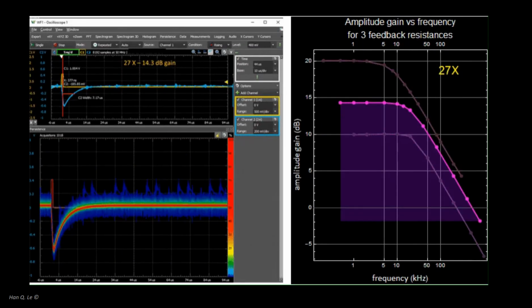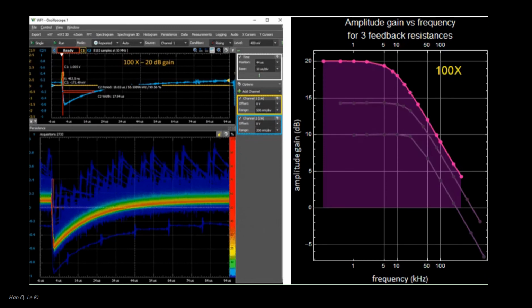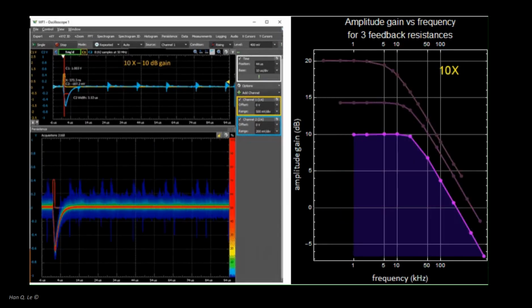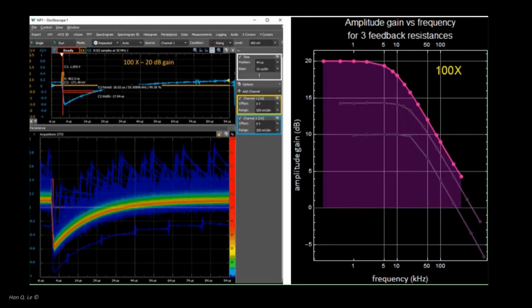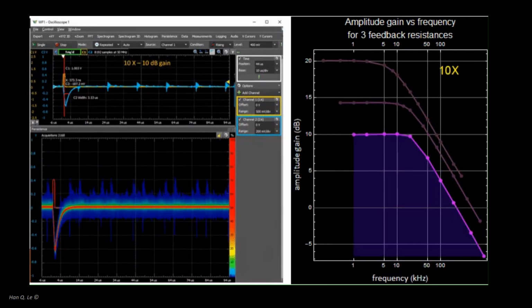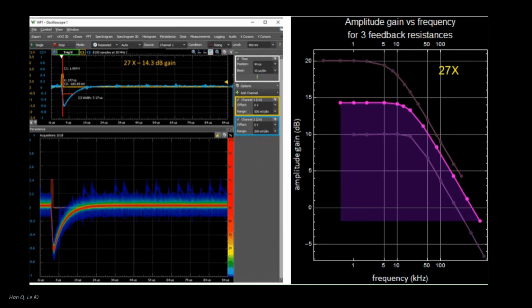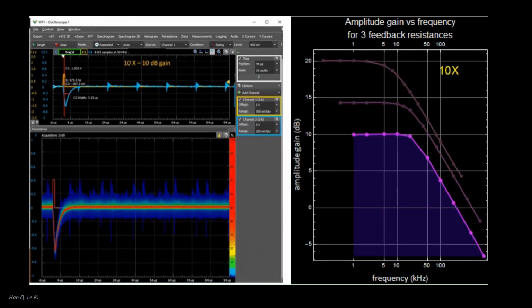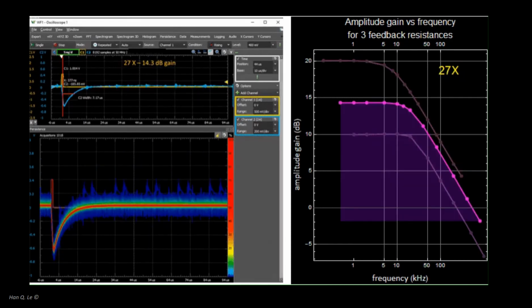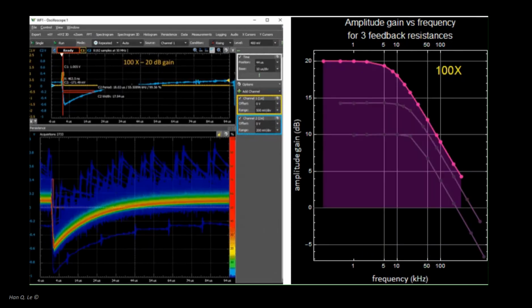As expected, there is a correlation between time domain measurements of the response on the left, versus frequency domain measurements on the right. Similar to gain bandwidth behavior on the right, higher gain correlates with slower response on the left. For those who have learned signal analysis, there is an inverse relationship of bandwidth on the right versus time response on the left. Or, one can say that a fast time response on the left corresponds to a wider bandwidth on the right. For a linear system, this follows from Fourier analysis.